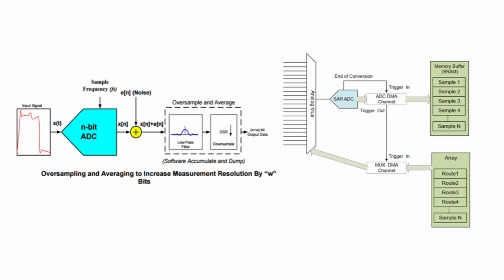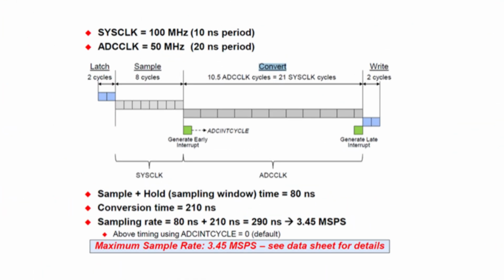Okay, so oversampling and filtering help with resolution and noise. What about that trade-off between speed and accuracy you mentioned earlier related to sampling time? Right. Let's revisit sampling time and the ADC clock prescaler. These are key tuning parameters. Remember that sample and hold capacitor inside the ADC? It needs time to charge up fully to match the voltage coming from your sensor. The sampling time setting directly controls how long the ADC's input is connected to that capacitor before the actual conversion begins. It's often measured in ADC clock cycles. What's the practical trade-off when setting this time?